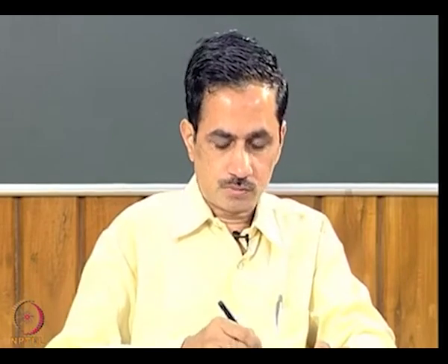With that as background, we will see for a bigger system how we can get the instability directly by looking at the eigenvalue of the system, in which, in the more general case, when we are considering damping and other effects, we expect a real part and imaginary part of the eigenvalue, and we will see that by plotting them as a Campbell diagram, how we can find the instability in the system.